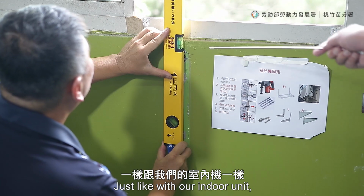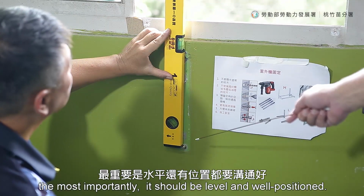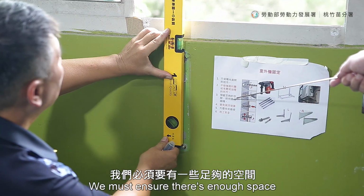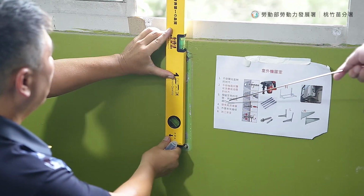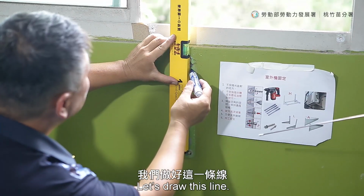Just like with our indoor units, aside from being secure, the most important thing is that it should be level and well positioned. We must ensure there's enough space for proper ventilation. We don't want hot air blowing out and getting blocked by obstacles. Now we'll screw in the expansion bolts. Let's draw this line.